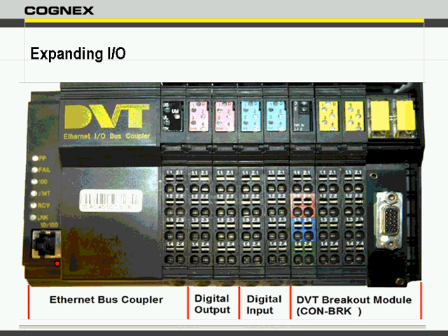So what you'll notice here is we do have an Ethernet connection to connect to this, and then we can gain 8 more. This is going to be power for these modules. So we have here 1, 2, 3, 4, 5, 6, 7, 8 in output. And again, the same thing over here with our input. So we're going to gain 8 more input and output.